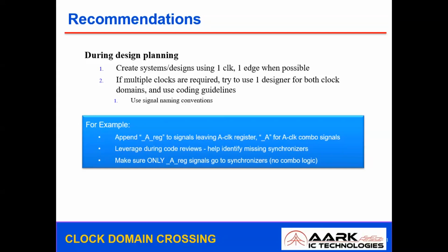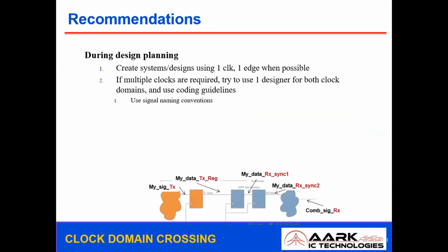So these are the synchronizing elements. These signals must be properly synchronized. If they are not properly synchronized, we are going to face metastability issues. It might violate setup and hold times. Therefore, the designer will understand and make sure that proper synchronizing methods are applied across these clock domains. Make sure only a registered signal goes to the synchronizers. Now if you look at this, my signal TX transmission has passed through this clock domain.